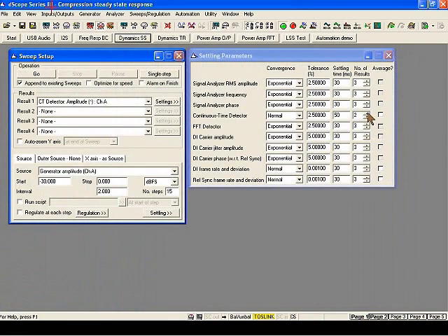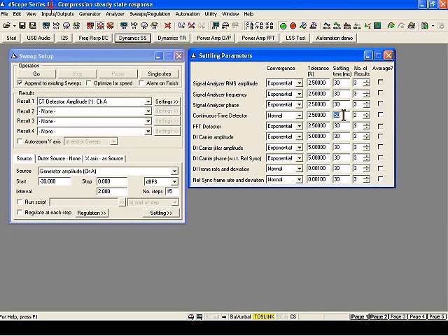And of course I've had to be a little bit careful because this will take a certain amount of time. One of the parameters on the compressor is the attack time, and I've had to ensure that I've built enough settling time into the analysis routine here to ensure that the compressor has settled to its steady state amplitude before I ask DScope to make a measurement. So I have assigned a settling time of 50 milliseconds here, knowing that my compressor settling time is about 20 milliseconds.